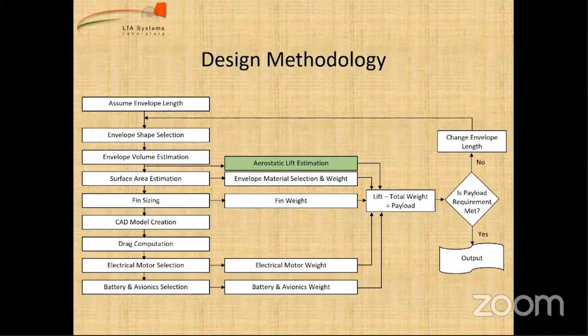So bigger value minus smaller value, correct? Always remember that the lift force that any envelope with LTA gas inside it generates is a result of the difference in density between the ambient air and the gas inside it, multiplied by the volume, of course, to find the weight force. So force is essentially the lift.